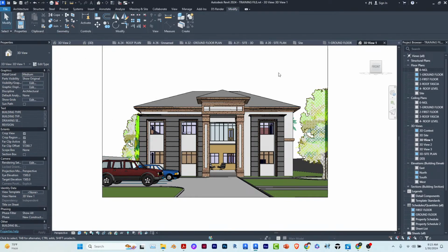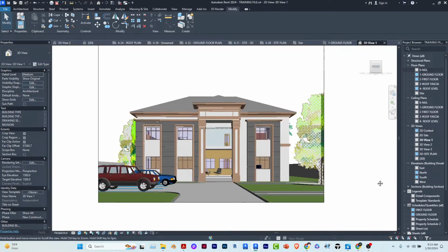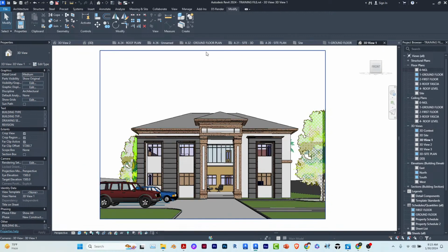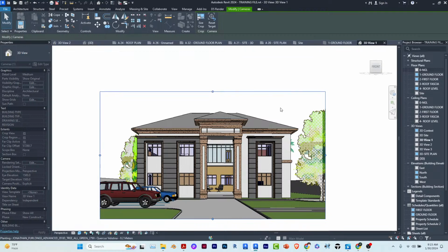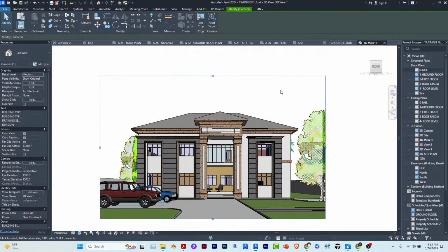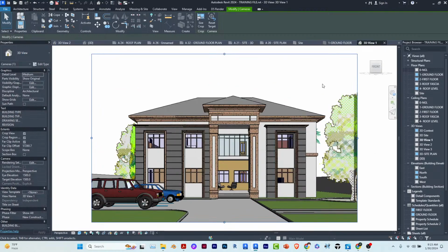Good. After this, for you to render this view, you might want to do some settings. Now, Revit basically is not a full-time rendering software, so you won't blame them. To render this view, you click on the render icon somewhere down here, this kettle, show rendering dialog box.